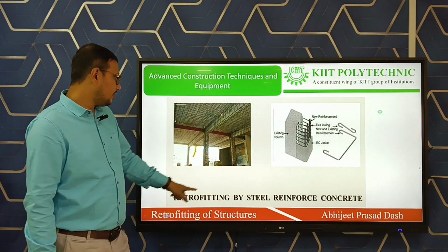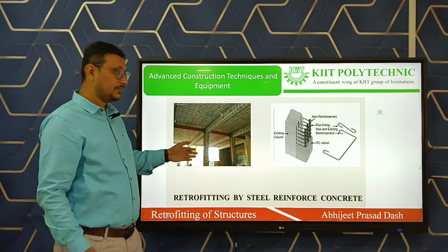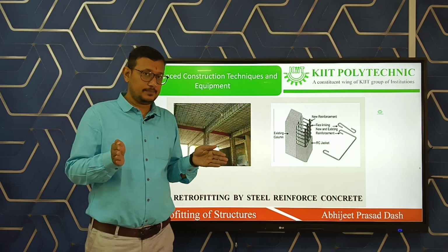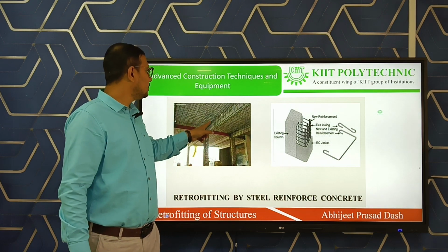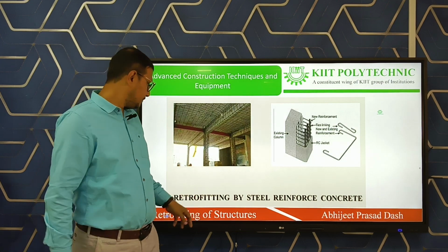You see retrofitting by steel reinforced concrete. We are adding another layer of RCC to the columns, to the beams, to the roof as a whole, making it stronger.